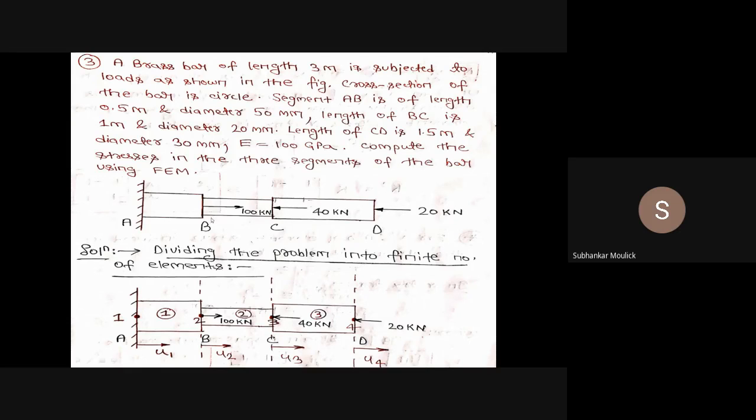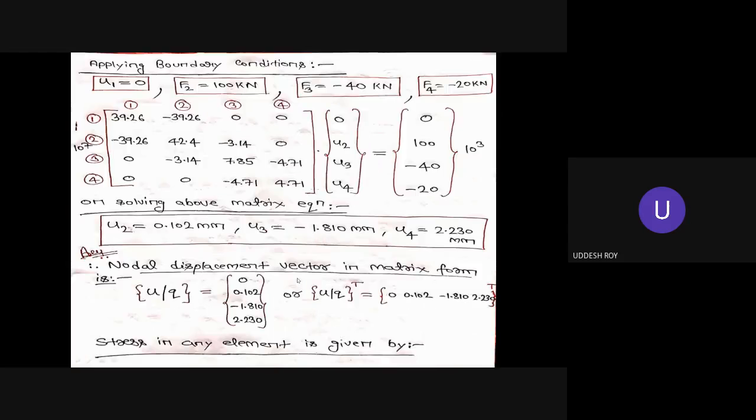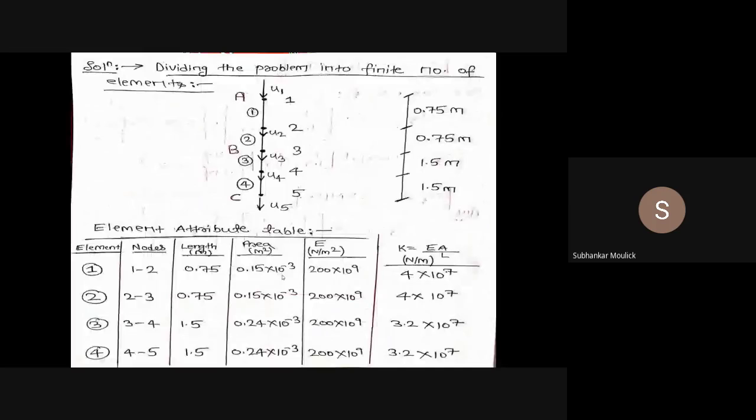And the second difference is there is no clearance, since the bar is not fixed at end D. So there is no story of clearance in that problem. But in the current problem which we are solving, the lower portion of the bar is fixed at a certain distance. And that distance is 1.5 mm.